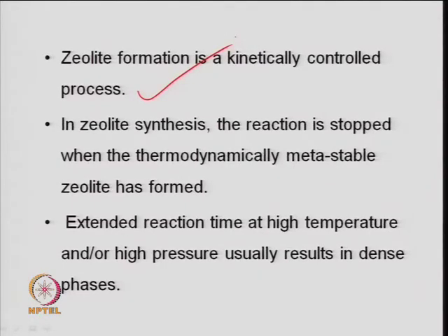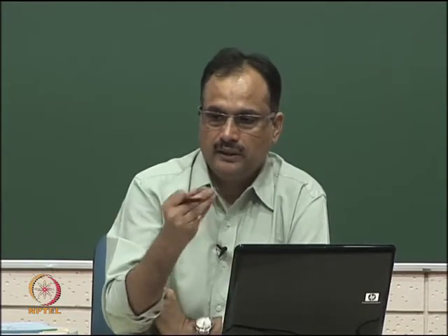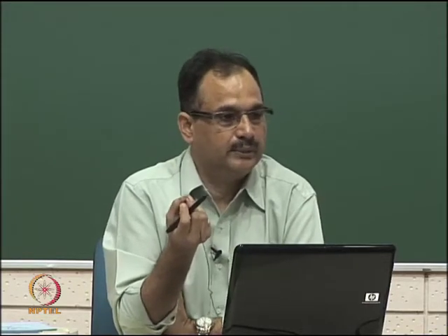Then you have to give enough time, the reaction is kinetically controlled, and based on that you have to identify whether 24 hours or 7 days, sometimes 20 days, right. Because the kind of silicate to aluminate framework which is forming depends upon the raw material, you have to look at that. In fact, from time to time you have to take out your sample and take the XRD and compare whether you are getting what you need, because these should be highly crystalline materials, right.